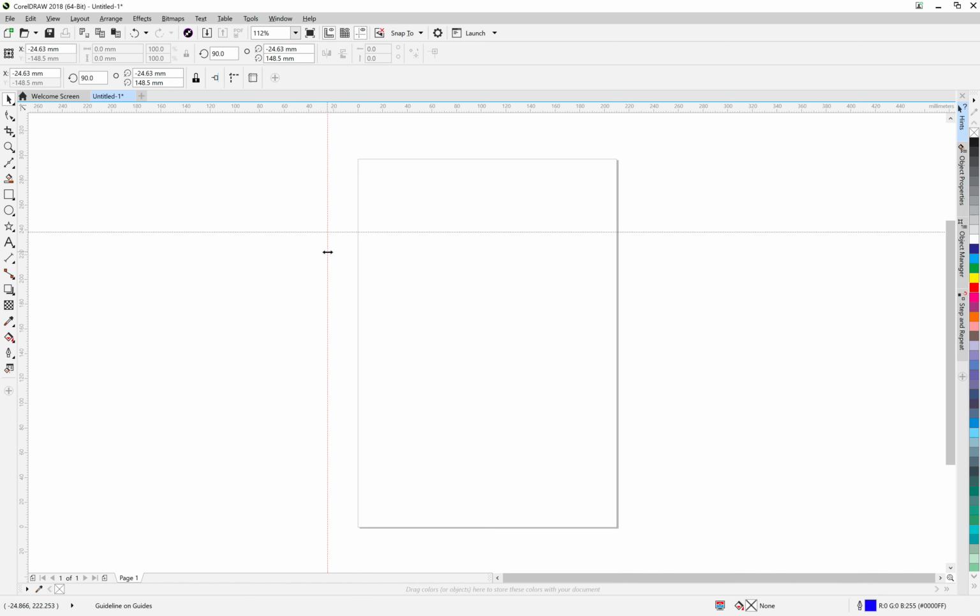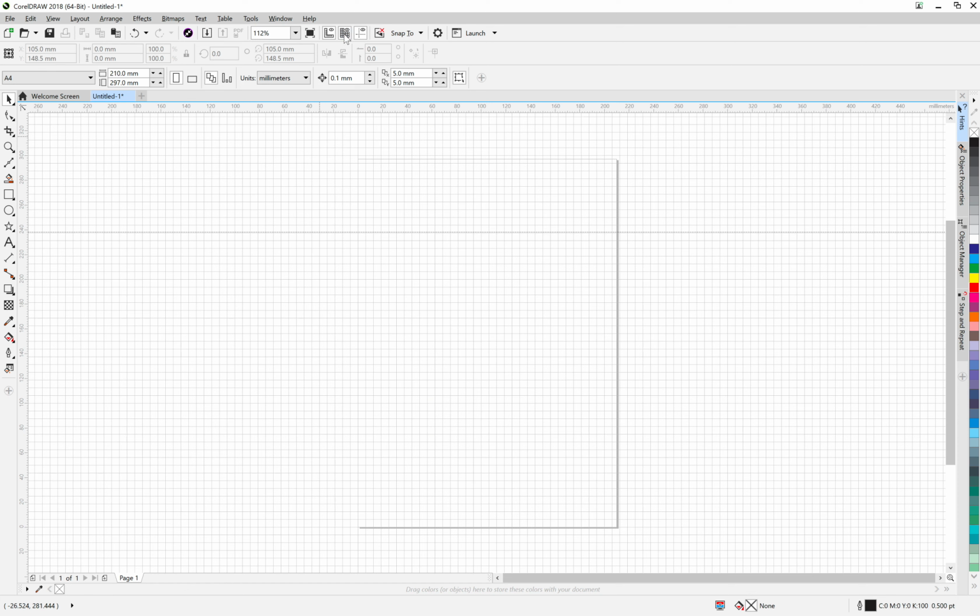If you want to get rid of them, as long as that's highlighted red, you can press the DEL key and delete it. At the top here again, you've got show grid. I quite like the grid tool, it's sometimes handy. And if the grid tool is there, then you can also snap to the grid, which is handy as well. So if I click on this particular menu drop down at the top there called snap to, I can say document grid.